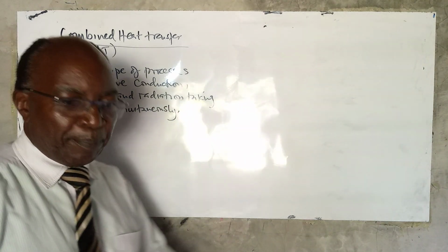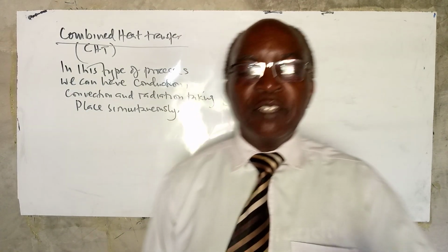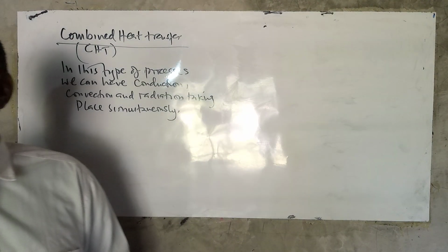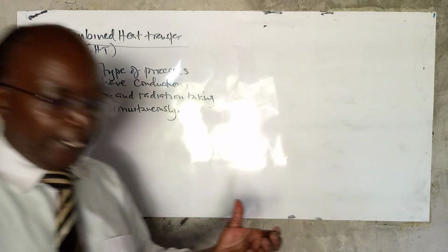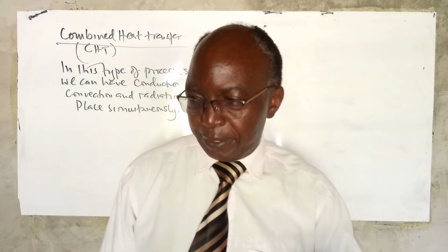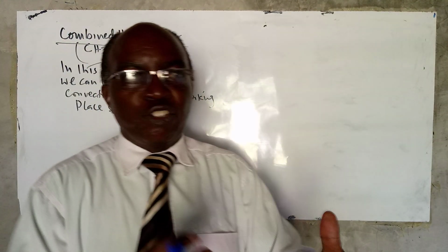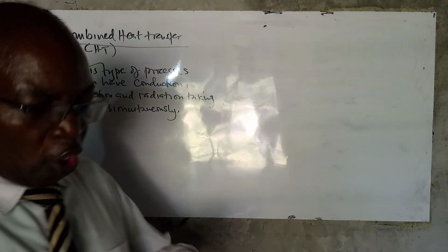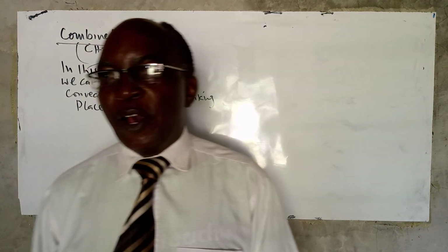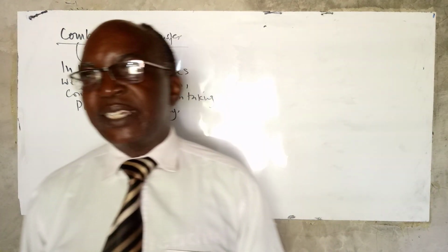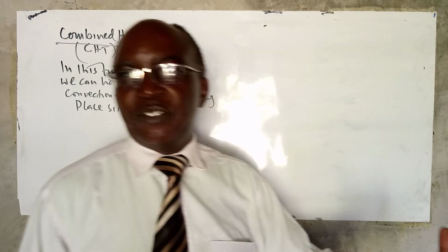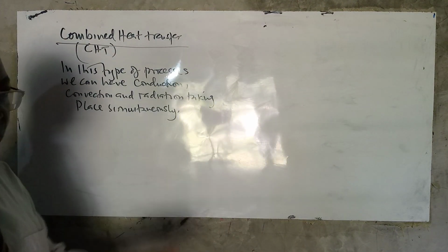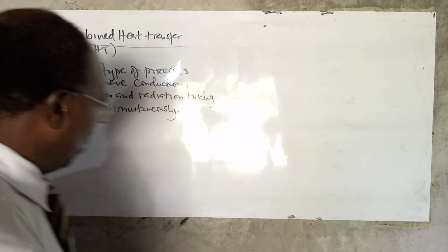The key question is, suppose now when you want to calculate the rate of heat transfer, what heat transfer coefficient do you deal with? Is it the sum of the individual heat transfers associated with the individual processes, or is it some function or form of it? So the most logical and straightforward assumption will be that you can actually sum the heat transfer coefficient associated with the individual processes. Unfortunately, it doesn't give you an exact solution.